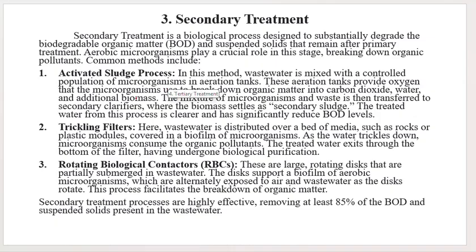Now let's move to the secondary treatment. Secondary treatment is a biological process. Please remember, the secondary treatment process is also called the biological treatment process. In this process we use a biological process designed to substantially degrade the biodegradable organic matter and suspended solids that remain after primary treatment.